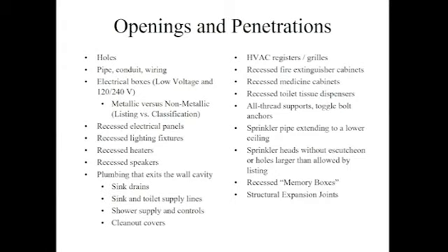Just FYI. And then there's other things, plumbing and such, that exits the wall cavity. You've got sink drains and supply lines and showers, the valve controls, clean out covers, all that kind of stuff that you see. You don't even think about all these pipes that stick out of the wall to plumbing fixtures. Well, they're all penetrations. They're all membrane. They're all coming down to that one side. They all have to be fire stopped if it's a bearing wall, or if it's a barrier, and that's no discussion.